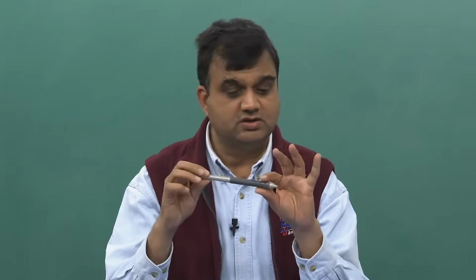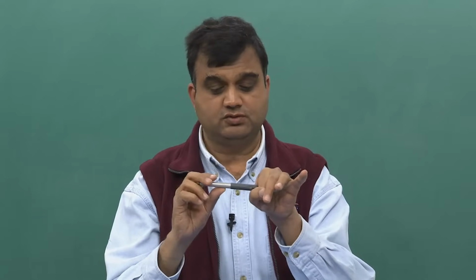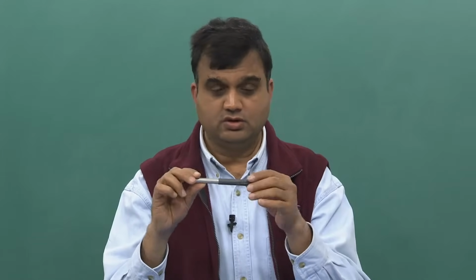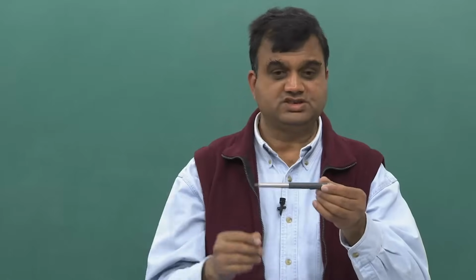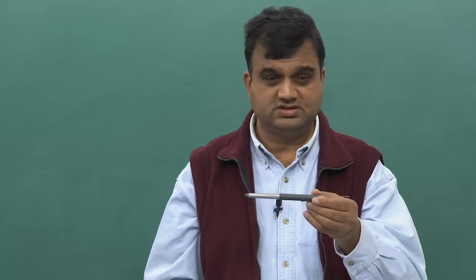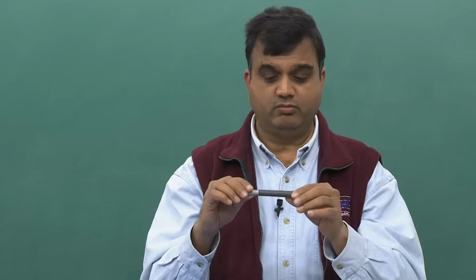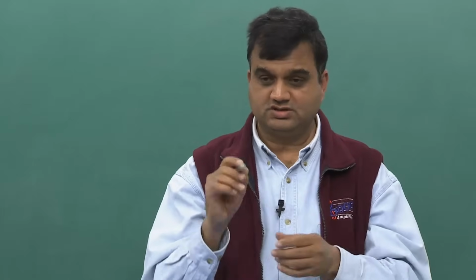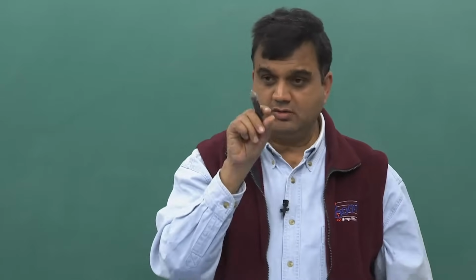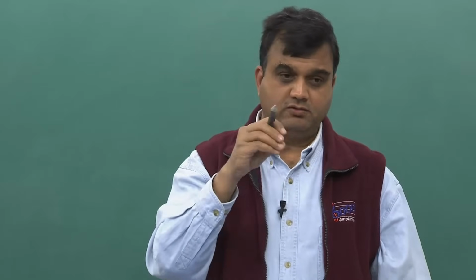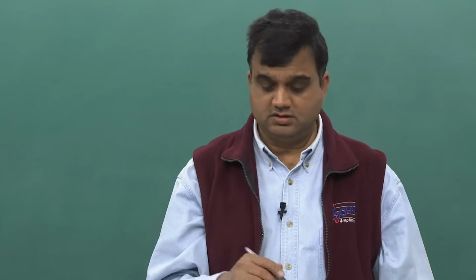For instance, in the case of the beam, what is it that we are trying to do? We are applying a force, and as a consequence of this force, the structure is bending. So, I am trying to develop a set of equilibrium equations, because there is mass here, there is stiffness, there are forces, and Newton's laws tell us that this thing will bend and move only if the external forces on each small element of this material are not 0. So, I take a small piece of material, I see what all the forces on it are, and then I develop an equilibrium equation for it. So, that is one thing.